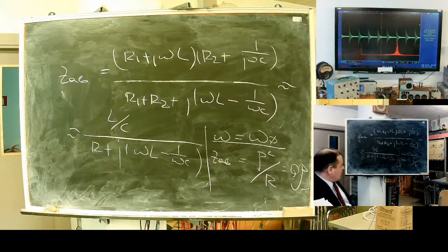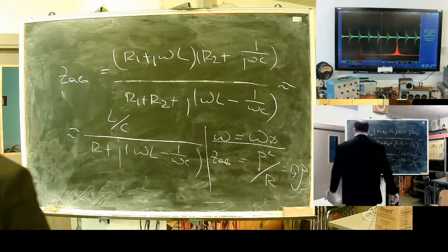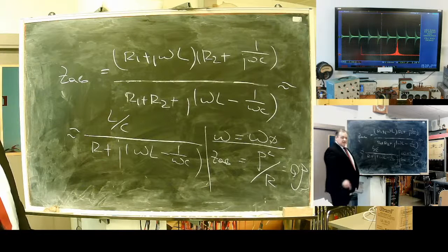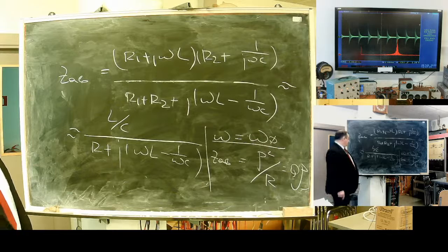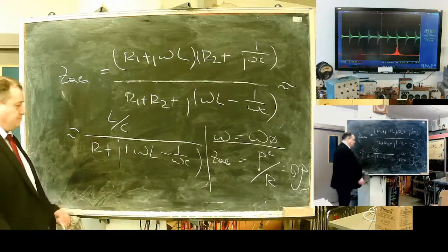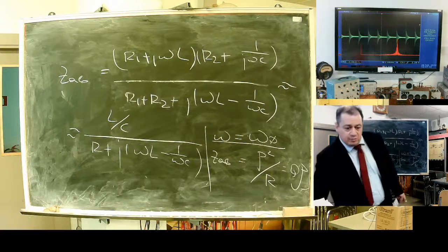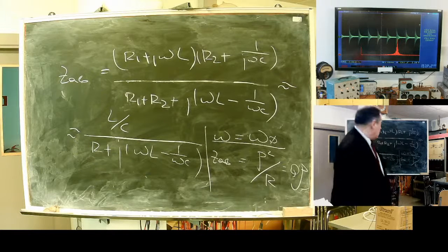It's the characteristic resistance squared divided by active resistance. So that is the active resistance of the coil. Yes, in general it's the coil plus the wires connecting the capacitor to the network. Okay, I'll prevent doubling of sound.